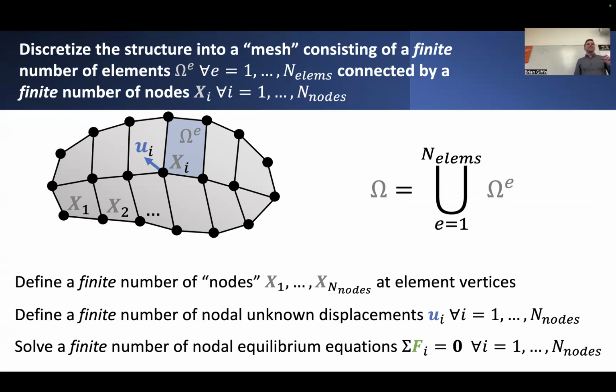We can take our original domain omega and we can partition it into just a collection of simpler shapes. And specifically in this two-dimensional example, those simple shapes are really nothing more than quadrilaterals as shown in this example. Oh, we have one triangle here. Well, we'll give that triangle some credit. Anyway, so it could be quadrilaterals, it could be triangles, it could be any shape you like, as long as you can reasonably describe what happens over the interior of each one of these simpler shapes.